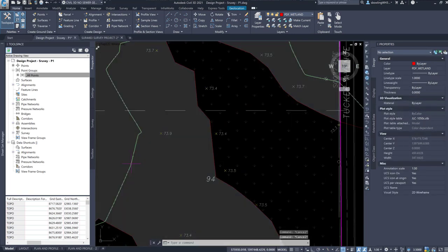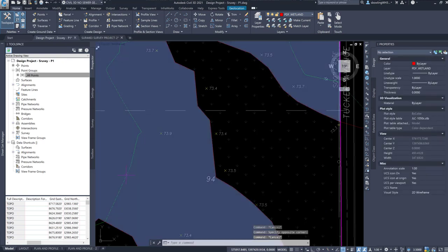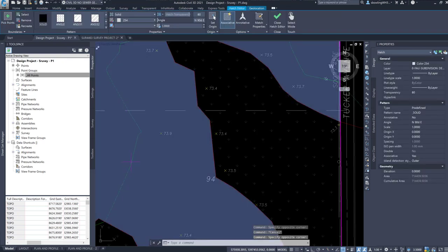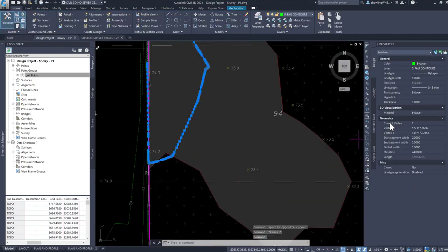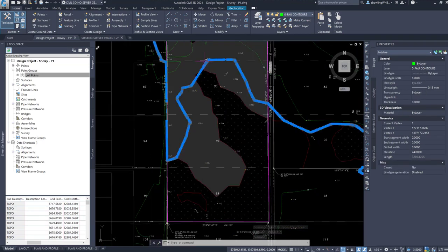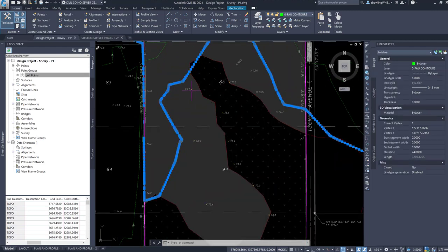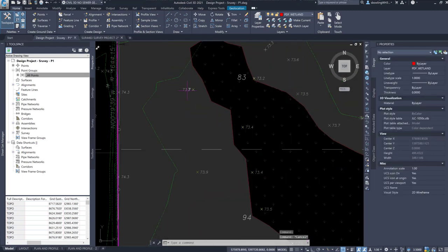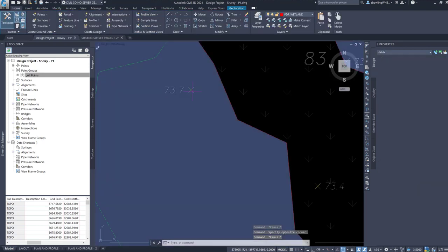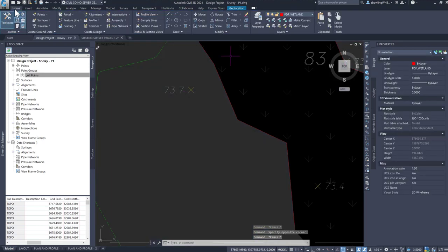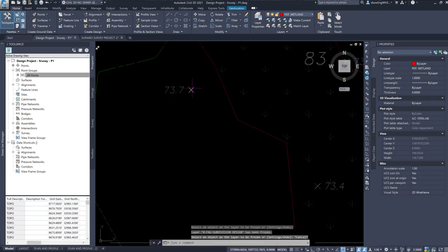These lines here are polylines, which are basically our contours. Okay, oops, I'm clicking on the wrong thing. For example, right here. These are polylines that have an elevation to them, and that elevation we will turn into contours. These here are points that we're going to use to include in our survey. I'm going to go ahead and freeze off this because I'm clicking on it too much.